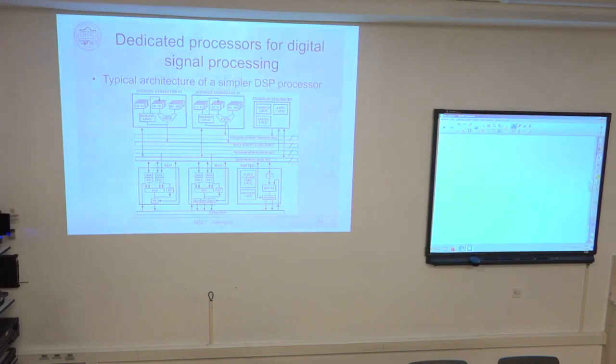I can shift the value by any given number of positions left or right in a single cycle. So for example, I want to shift this value 17 bit positions to the right. On a normal CPU, you would have to perform 17 shifts by one, one by one. Here, you have a single-cycle operation, simply 17 positions in one cycle. So it is called a barrel shifter.